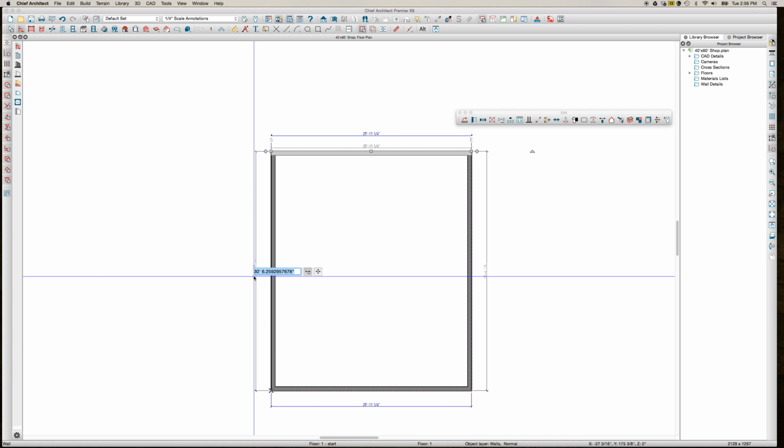foundation drawing. Now if I click this and open up, I can set here that this room supplies the floor for above. And so we'll set a few defaults here. We'll make the top of the wall B. We're going to set that to 8 inches because in this project I want my slab to be at grade level, and we'll call 0.